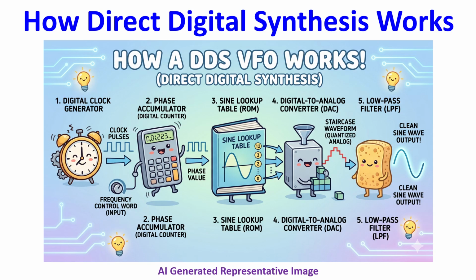One, phase accumulator. This is a digital counter that increments its value at every tick of the master reference clock. The amount by which it increments is determined by a digital frequency tuning word sent from an external microcontroller. Larger increments mean the counter wraps around faster, resulting in a higher output frequency.